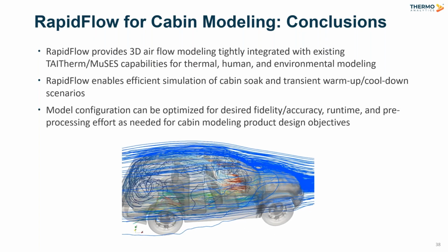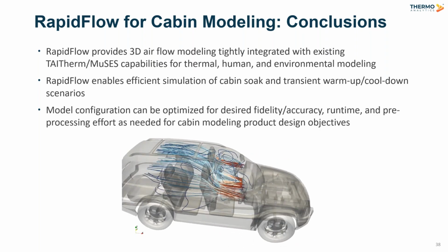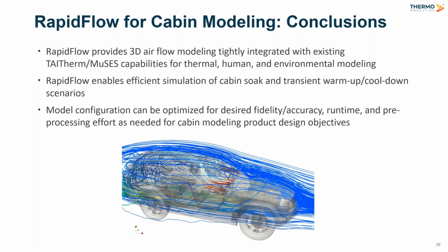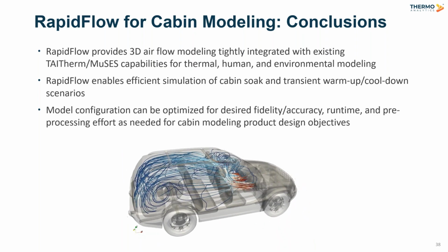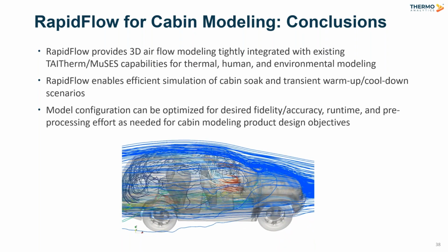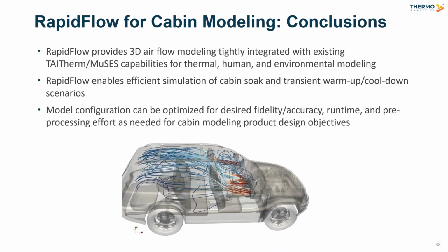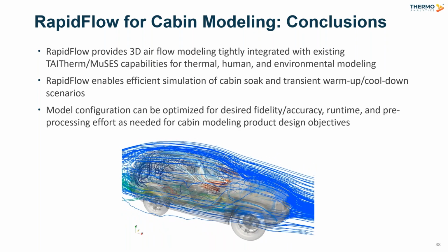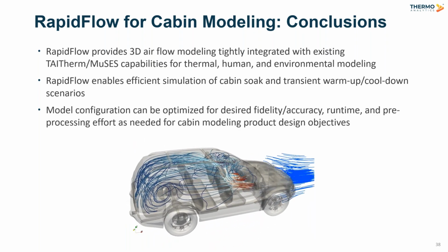Given the scaling that is possible on many CPUs, even in the current version, before we've got some of those mesh refinement features that I was talking about, if you've got a high number of CPUs, you can still turn around these models pretty quickly, even with a very small cell size. The smallest we showed for this cabin example was only about 18 millimeters, but it's perfectly practical to go down to 10, 5 or smaller, especially with a high CPU count.